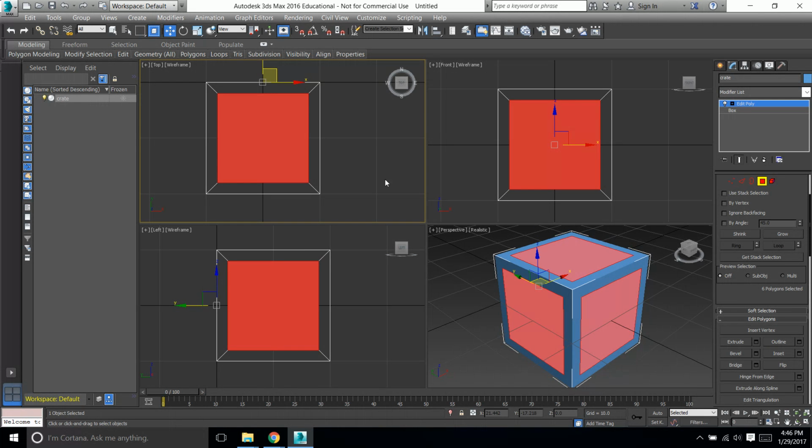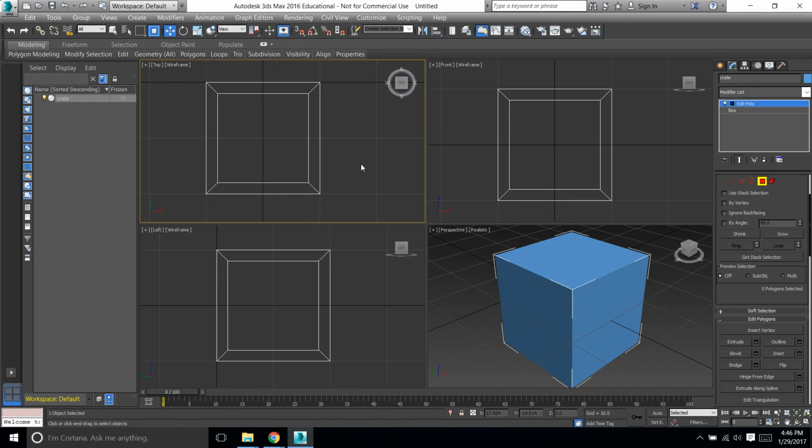All right, our second step in here is we're going to create a couple of new vertices. To create a couple of new vertices, what we have to do is go back to the edge face, and you can see on the edge face there's something called Insert Vertex down here. So I'm going to click it. I'm going to go to one of the edges as close to the middle as I can figure, and I'm going to just pick it here, I guess, and hit insert there, and I'm going to do another one here.